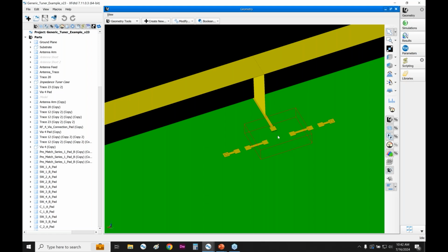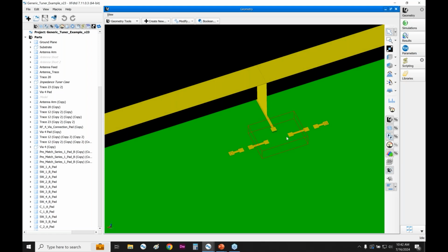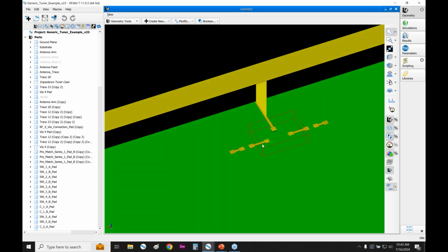So in this case, we're using an aperture tuner, which is essentially a switch where we have the RF feed coming into the antenna, and this red box is just a cuboid with the faces set invisible, and we drew red lines for the edges. So that's all that we're visually rendering here, but it's supposed to represent the chip. And so the chip has 3 pins. There's the RF connection to the antenna, and then there's a switch in here, which we switch between the left side or the right side.